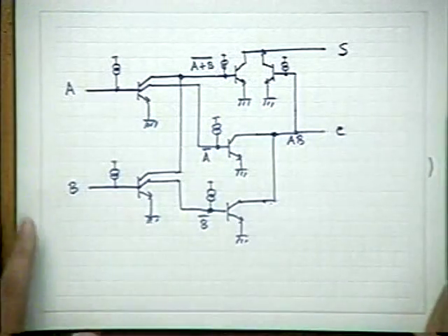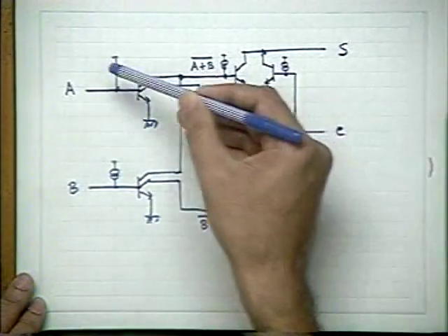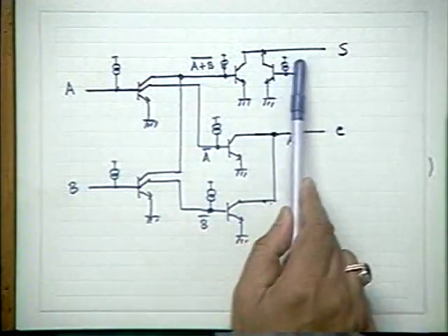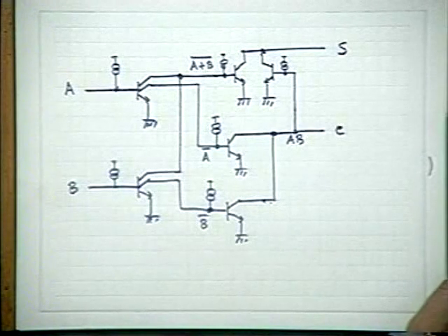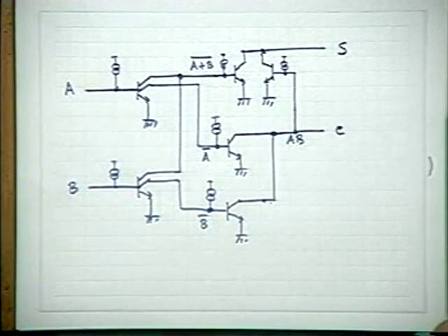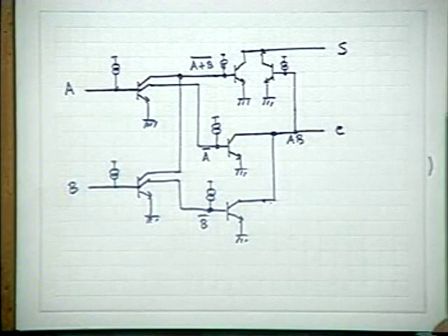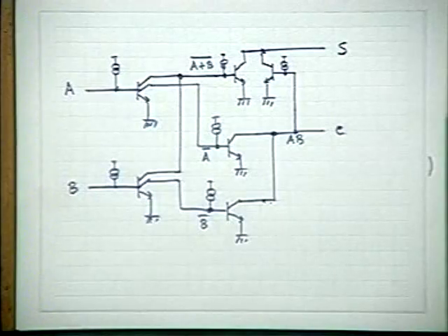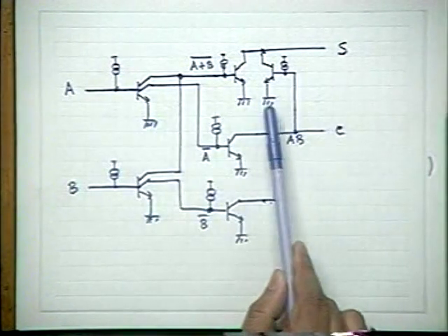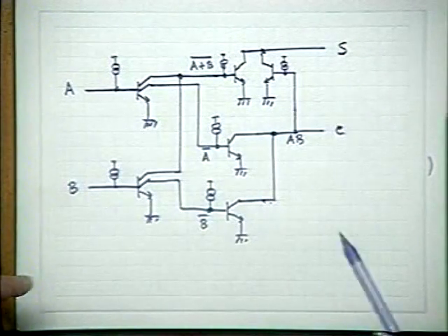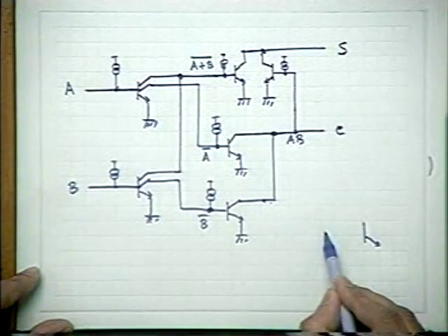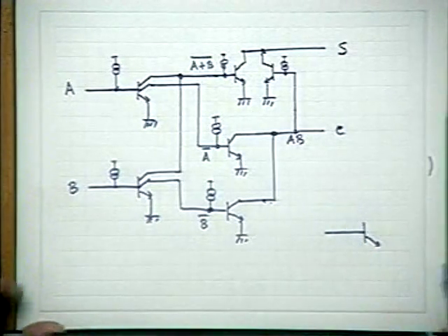How to realize? Actually, I have shown. Please see that these PNP transistors are all distributed, which are not indicated in the diagram. I will find afterward, if you just go through any papers, a Journal of Solid-State Circuits, recent papers, or even 10, 15 years ago paper, you will find that for simplifying the circuit diagram in I2L, they do not show the ground. The emitters are just shown like this, just floating. And here also they do not show the injector.